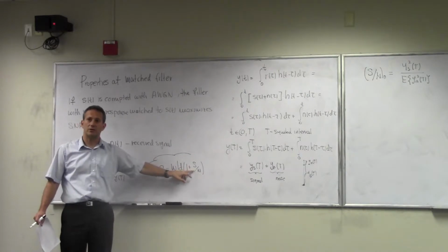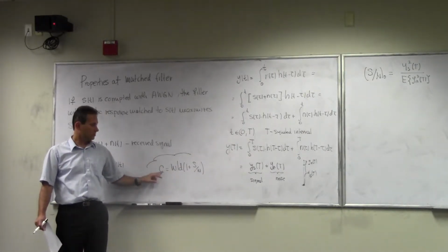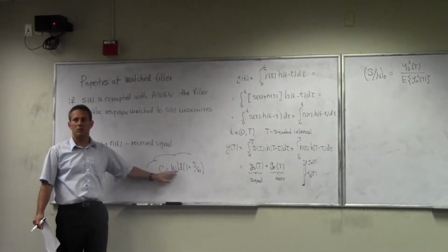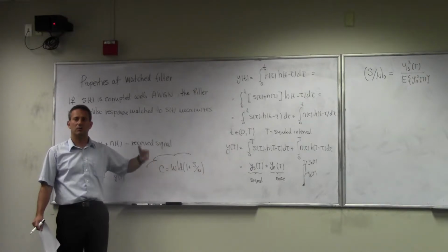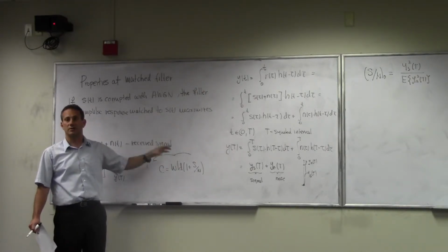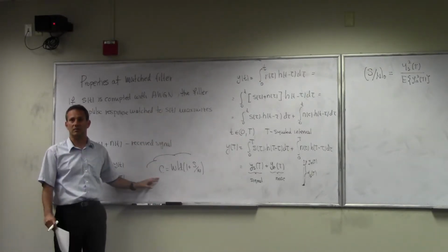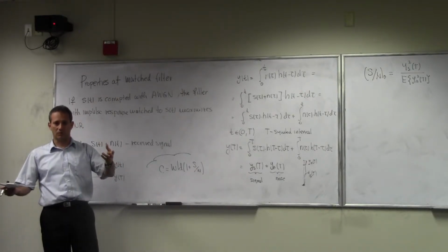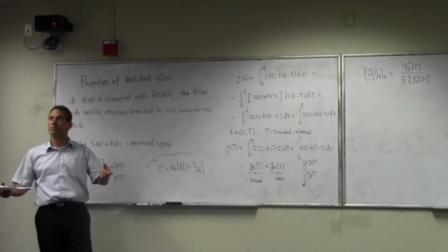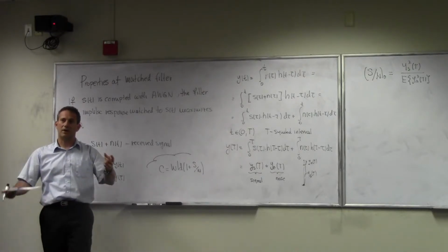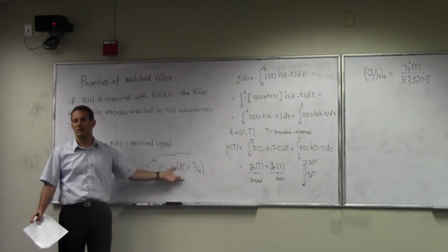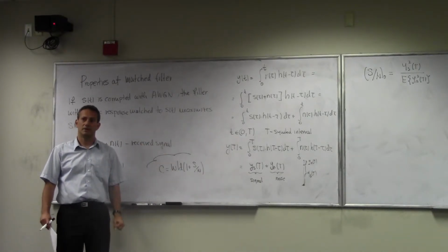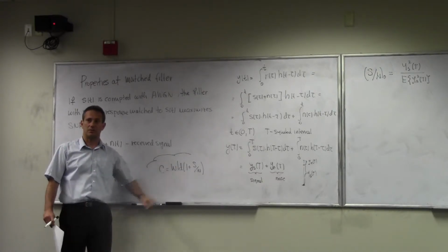Of course, if the signal to noise ratio changes, your ability to send more bits changes as well. And we all know that. This is where adaptive modulation and coding comes from. As your signal to noise ratio changes, modern systems change the constellation, and as a result your data rate goes down, even though the bandwidth you use is the same. An example is Wi-Fi: if you want real good throughput, you go right next to the access point. Because if you don't have enough signal to noise ratio, the modulation scheme will be selected to be, say, BPSK or QPSK as opposed to 16 QAM or 64 QAM. So that's directly proportional; it's just that the relationship is logarithmic.